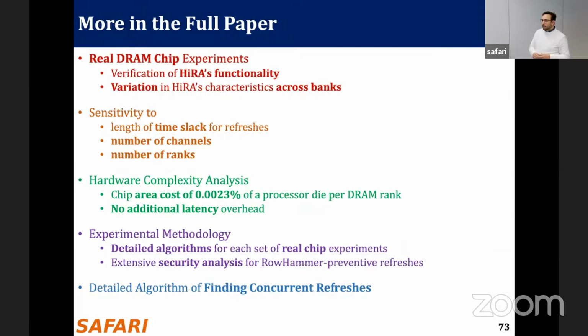And once they officially support this, they can also build very low overhead mechanisms in subarrays and row decoders, and they can easily parallelize all these operations internally as well. You can pretty much hide all these maintenance operations that way.